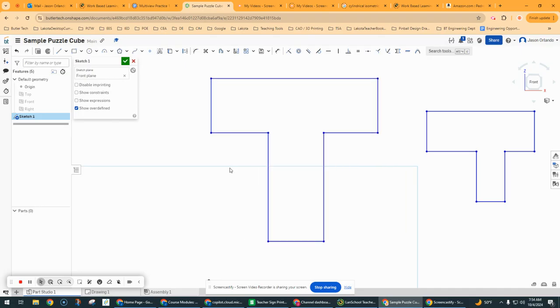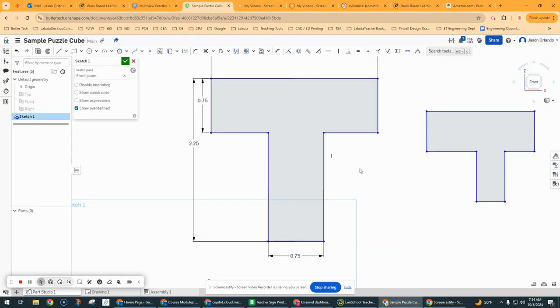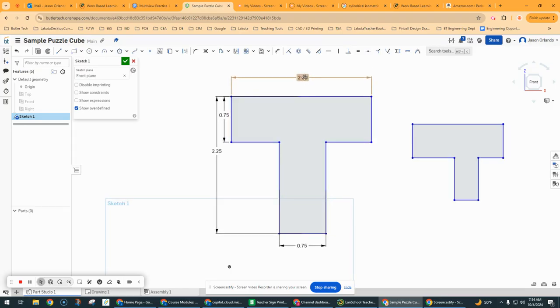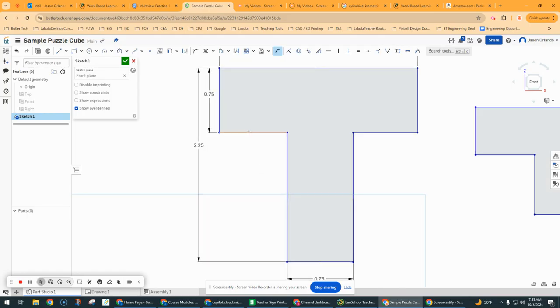We know we want it to be centered, where it's kind of 0.75, 0.75, 0.75. Well, we already have constrained the overall width. So if we get one of these constrained, then the extra is over here. And so 1 block of width right here being 0.75 would basically be the length we need for this line segment, or the distance from this line segment to this line segment. Both are going to give us the exact same result, so it really doesn't matter where you click, here or here and here. It's just if you use these 2, you have to make 2 selections.